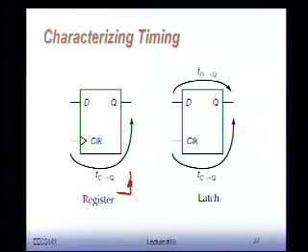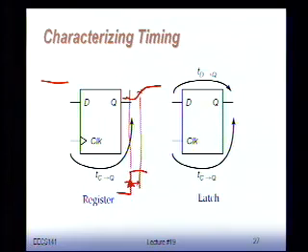Okay? So we have a rising edge on the clock, and you will see that if, let's say, the input is high and the output is low initially, a little bit later the output will go up to 1. It will sample the input and send it to the output. So you take your 50% points, same as before.